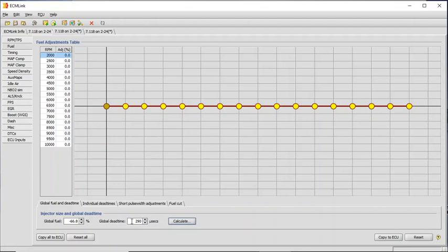So what I will say on this particular section here is, if you're raising global dead time here, that is giving you more fuel. Lowering this number here is subtracting fuel. More than likely, if it's not wanting to run, you may not be getting enough fuel. You may check your injectors, see if you're getting fuel. They may be squirting fuel, but it may not be enough. Okay.